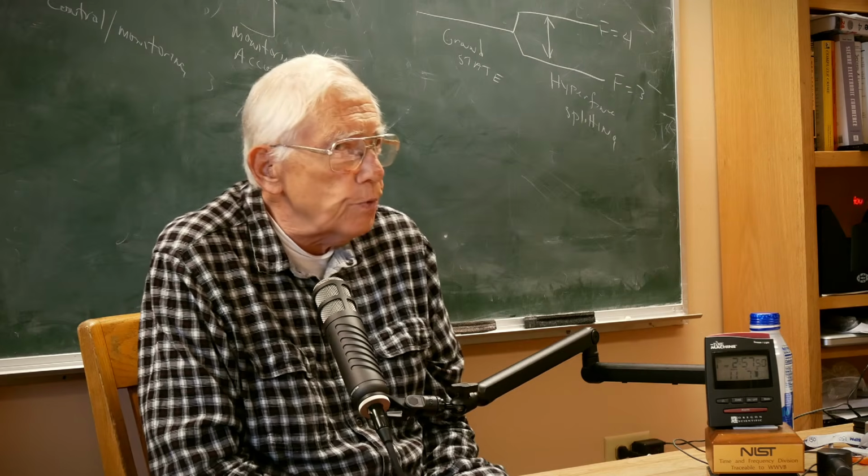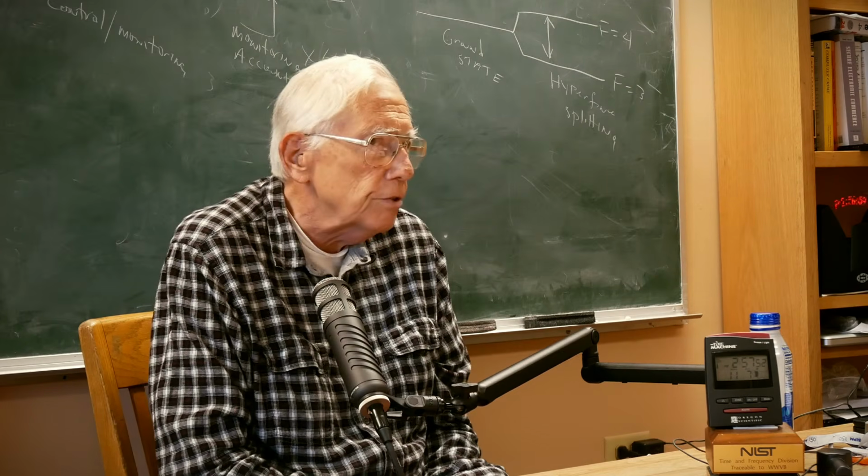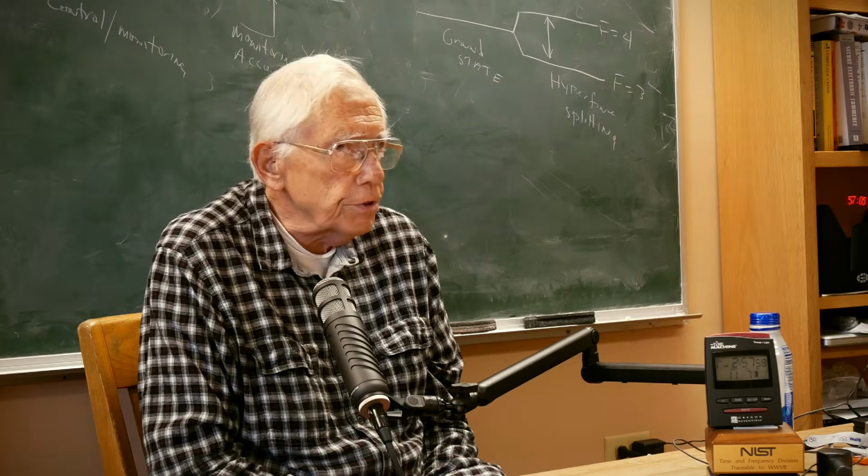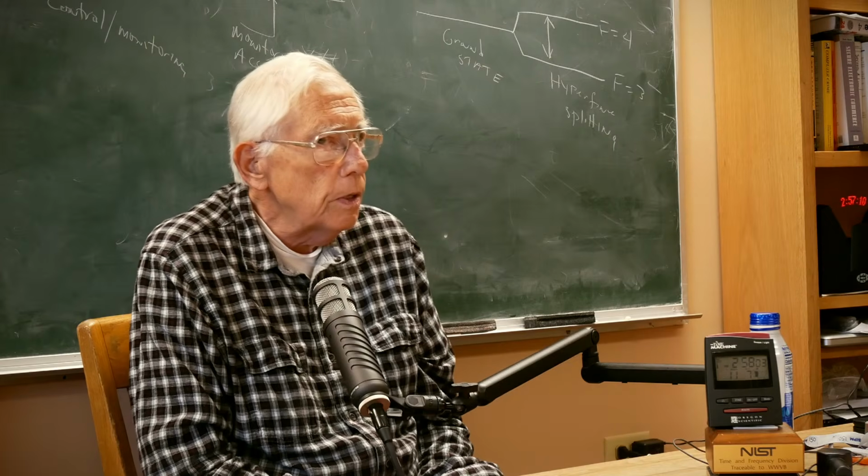So there's something that slows down, like if the quartz oscillator is in the megahertz range or something. Well, in a wristwatch, it's not in the megahertz range; it's in the kilohertz range. But the principle is exactly the same. So there's something that slows it down, where there's a down conversion from kilohertz to hertz. It's not a down conversion; it's a counting. How do you turn 1,000 beats from the quartz crystal into a single second-hand movement?